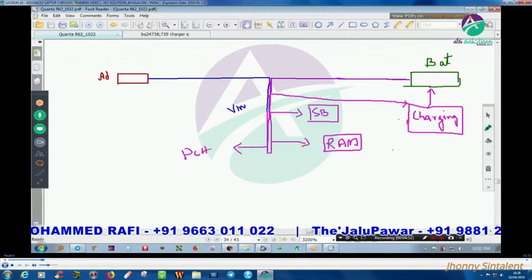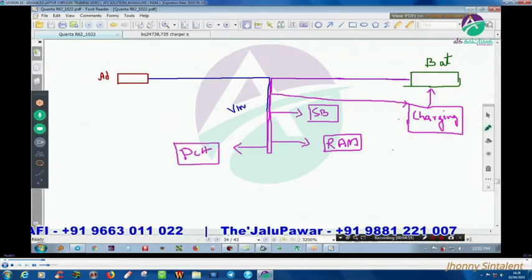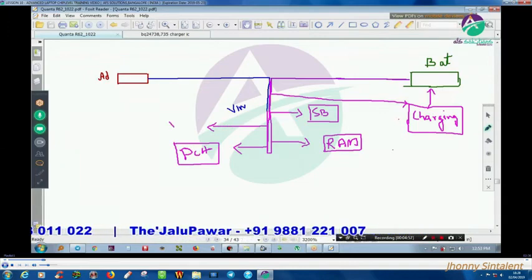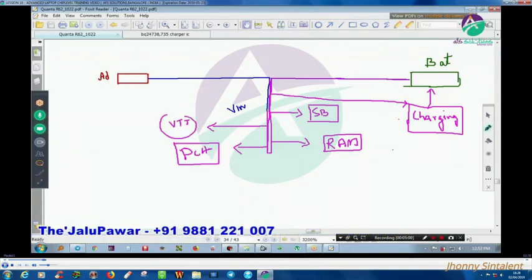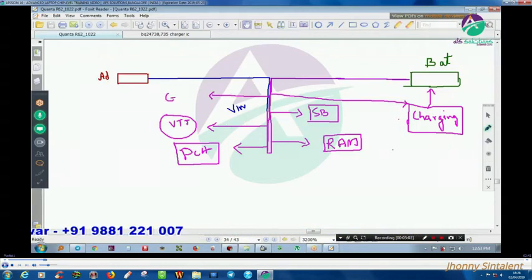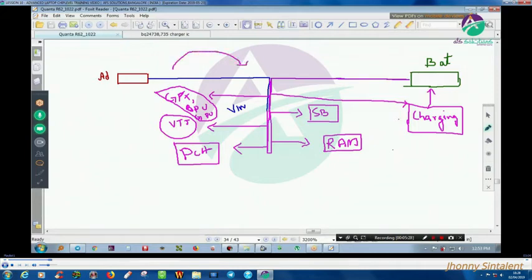This will go to PCH. This is common, you all know what I am trying to tell. This voltage will go to the termination voltage of the CPU. This will go to CPU core, GPU core and GFX core. All this voltage, that means this is the main path, it has to come. But what is the rule? Either the voltage has to come from the adapter, or this voltage has to come from the battery.